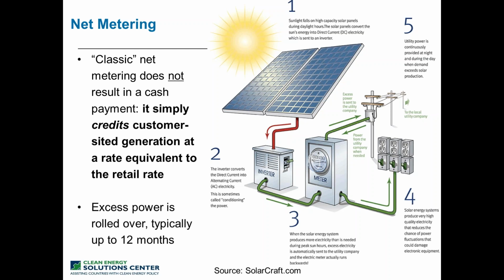The standard design is, and we come back to this at a later stage, that you can roll over the electricity for a 12-month period. So for 1 year, you're metering both your electricity consumption and your electricity generation from your rooftop, and by those means you can then say, okay, over this full year I have consumed this amount and produced this amount. This will be put together in your electricity bill, and you will only have to pay the difference, so the electricity consumption that you have at the end of the year. Of course, there's variations to this. This is just a very basic concept.